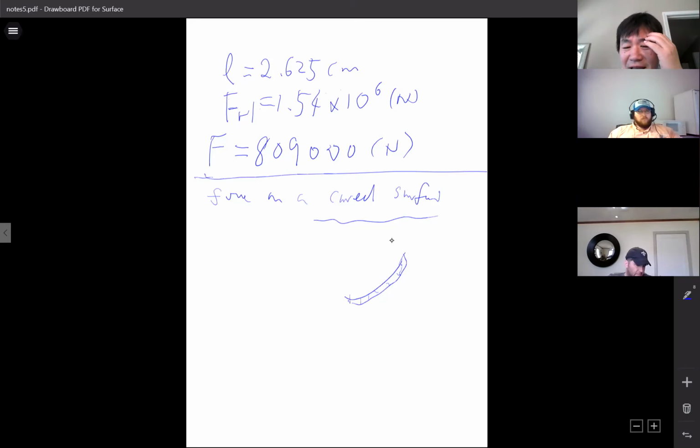Let's say on one side I'm holding it, and on the other side you have hydrostatic force, and it's balanced. So to calculate the force, I need to calculate the hydrostatic force, FH. We don't want to do this directly, because you have to do integration, pressure times dA.